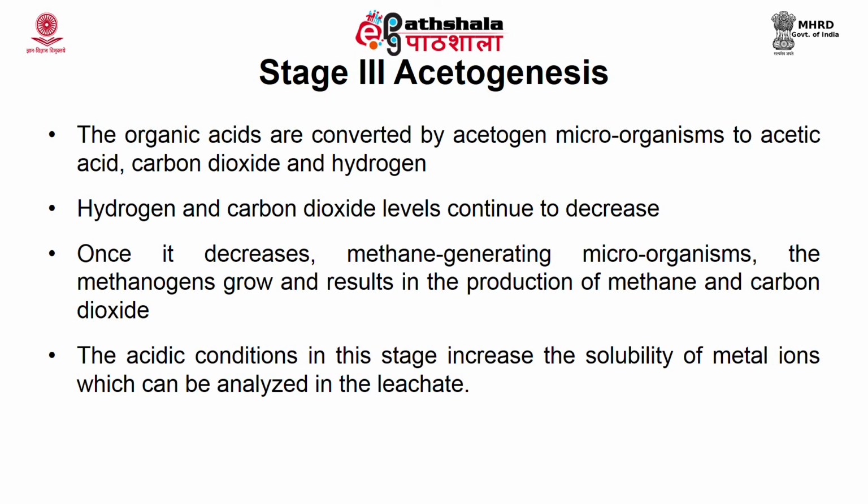To summarize this module, at the end of this module you would have understood what a landfill is, and what the different components of a landfill are, like the liner system, the waste emplacement cells, then the capping or the cover system. We have discussed in detail the different liner systems like the single liner system, the composite liner system, the double liner system and the multiple liner system. Then we also discussed the waste emplacement methods like the layer method, the cell method and the area method.